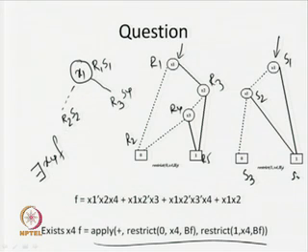That means, since it is a non-terminal node, we are going to create a node x2. Similarly, here R3 is a non-terminal node, but S4 is a terminal node. So, we are going to create an x2 node at that particular point. Now, similarly, I have to look for what the solid and dashed lines are. Like that you can use this apply algorithm and construct these BDDs. Okay. Now, after that we are going to get the resultant BDD.